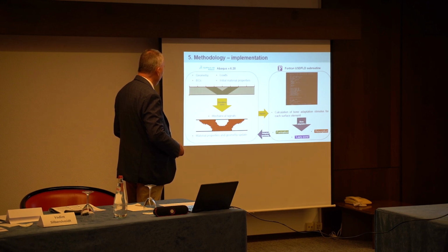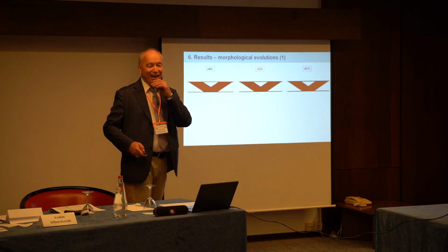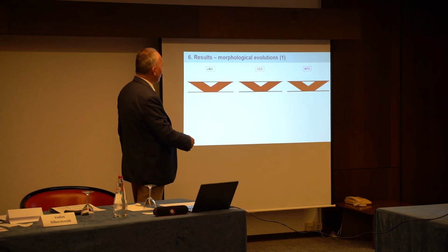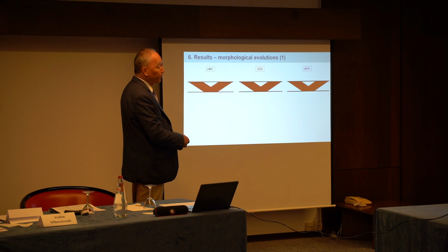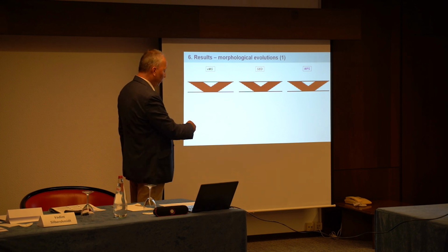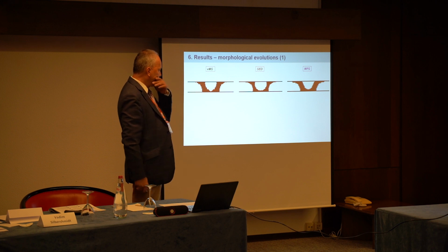Too many animations for my liking. Okay, these are the results of three simulations: von Mises stress, strain energy density, and major principal stress. The load is applied vertically to the bottom. And look at what is happening.